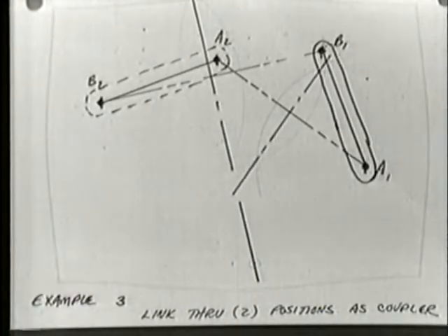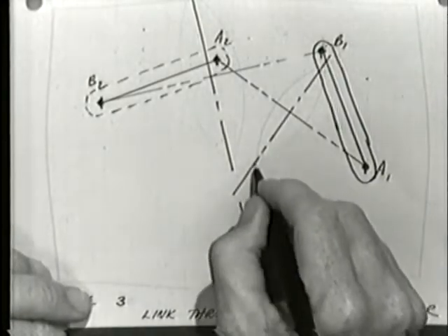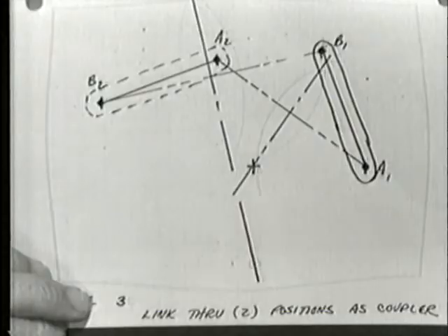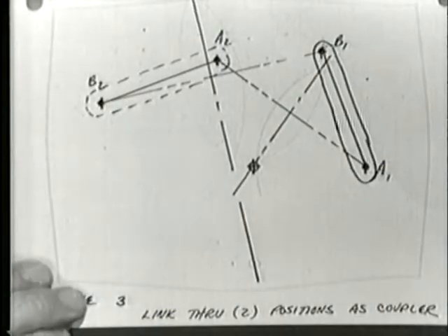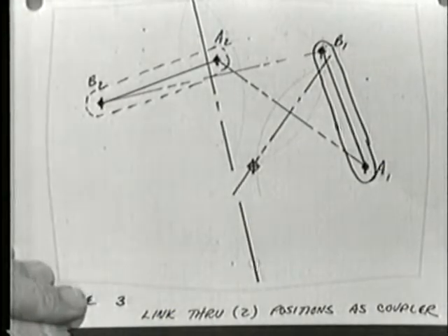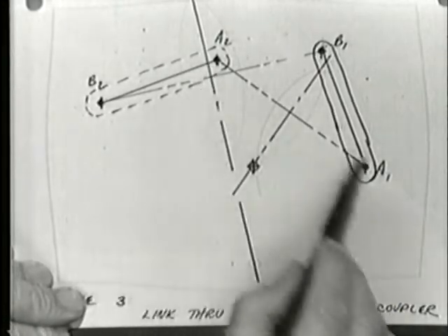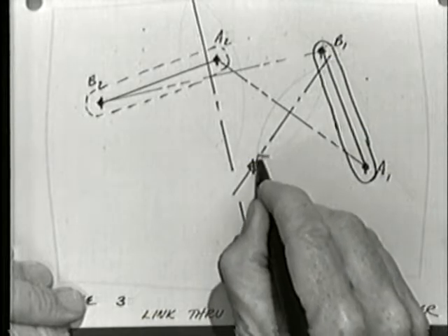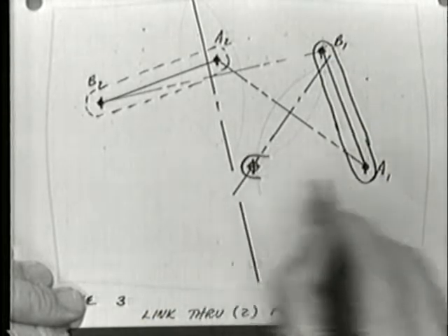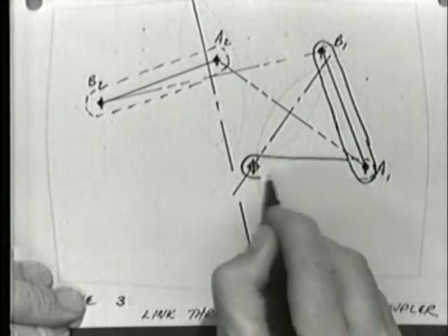So I can literally pick any point whatsoever on each of those perpendicular bisectors, and I have a potential pivot for my other links. So I'm going to pick a point right there, very arbitrarily, just as a guess. And since that is on the perpendicular bisector of A2, A1, then I'm going to create a link that connects that point that I just chose somewhat arbitrarily with one of the A's.